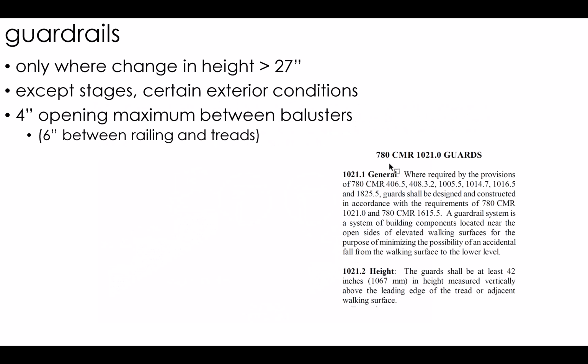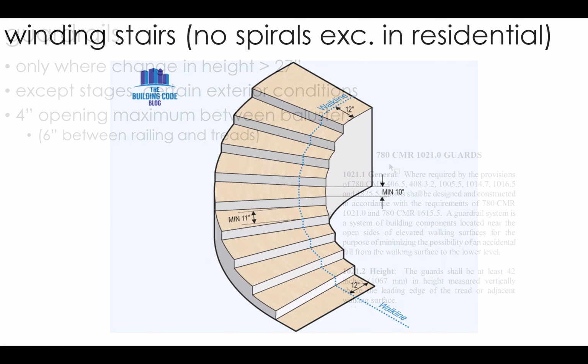So there's a lot of rules, including for the guardrails, which of course are also required anytime you have a stair height change greater than 27 inches, almost every time. So you do need to make sure that whatever custom design you make, that they comply with these rules.